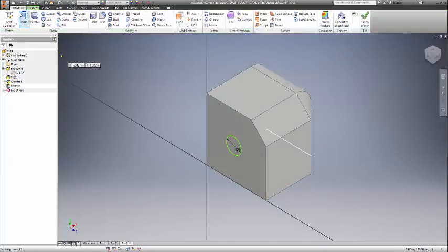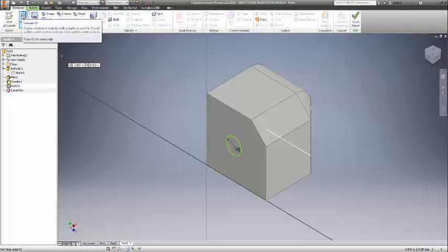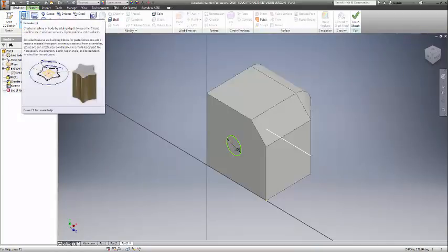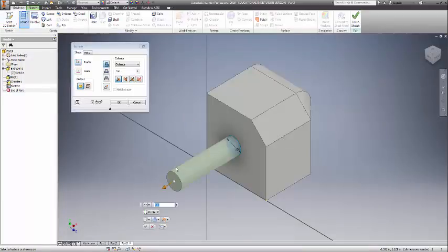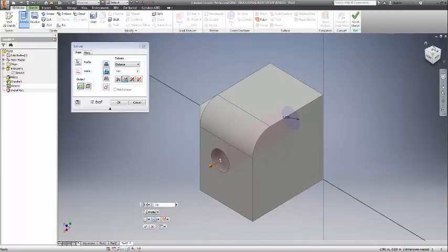and I'm going to Extrude. Now, we've used Extrude to make things out of it and make something. You can also do it to take away stuff. Okay, so in this case, we're going to Extrude, and you notice it automatically comes out this way. We want to do direction 2. Let's go direction 2. Okay, and we want to go all the way through it. Yeah, that's pretty good. That works.